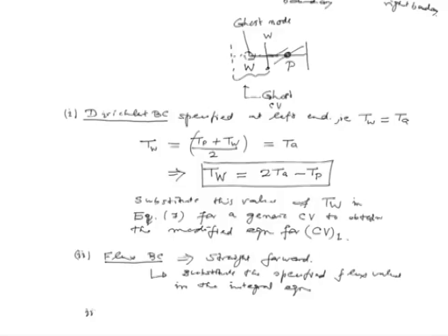If we had the convective BCs, so convective flux is specified, once again the process remains similar to what we had done with the flux BC. Go back to our integral equation, substitute that value, and there would be a small catch which we will get there. We have the value at the end point of the domain, that face temperature would be involved, and now the face temperature can be obtained using the straight line averaging procedure which we had used for our Dirichlet boundary condition.